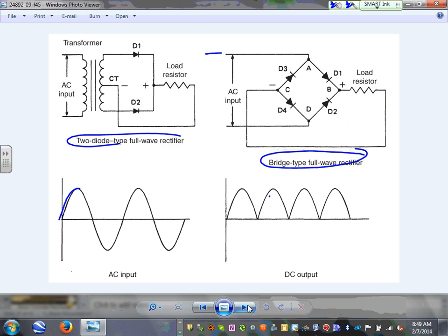So it goes this way, and when it goes the other way, it flips the voltage, so it becomes this way. And believe it or not, you're looking at a DC. This is a full wave rectification using diodes. I don't want to get into the diodes; they flip the voltage when it goes negative, just flip it over. That's the full wave rectification. That's another source, and then you put it through a resistor to limit the current and dump it across the load.